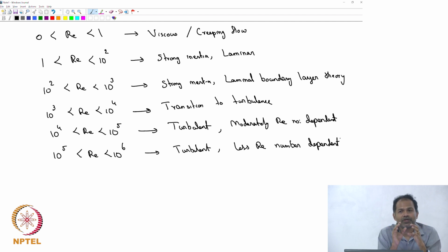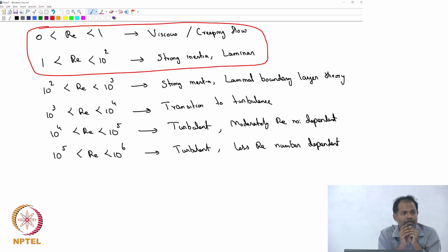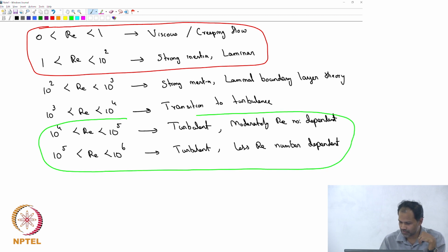The equations that we used earlier, the ones which we derived, are strictly for laminar flow. But typically when you go to large scales, you are going to deal with large pipes and large flow rates, and the flow invariably turns turbulent. Therefore we ideally would like to go to larger Reynolds numbers, and we really would like to go somewhere there. So we now need equations for that.